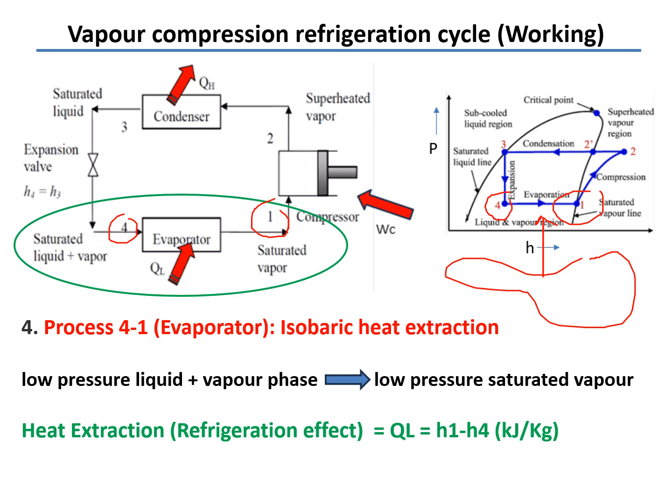So as that refrigerant is exposed to that particular space which you have to cool, it will boil, or you can say the liquid will convert into vapor. So at 1, that is totally vapor. It means that is a saturated vapor. So what amount of heat is added in that particular process? That is H1 minus H4, because here the enthalpy is H1 and here the enthalpy is H4. The heat extracted by that refrigerant, so that it converts into saturated vapor, will be H1 minus H4. And this is the refrigeration effect, by which you are maintaining some temperature below the surrounding in that particular space.